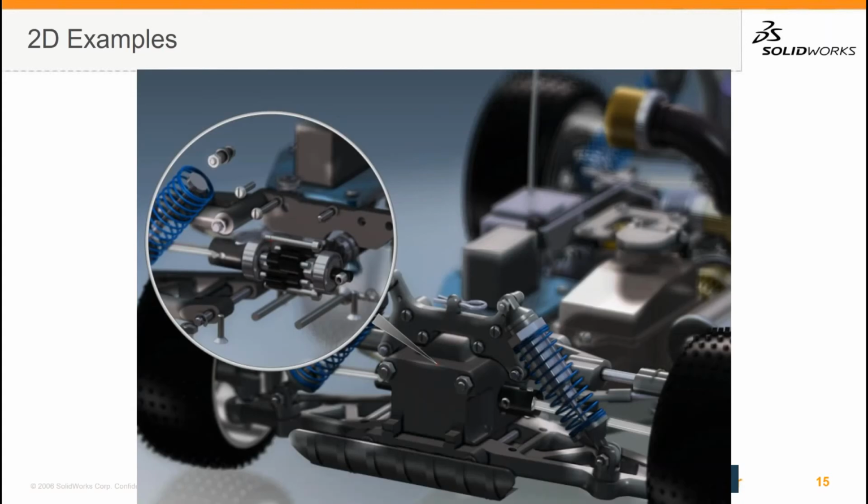And then we do even have rendering tools inside of Composer too, to do images like this. Set a depth of field to blur the background, a nice zoom tool here called the digger tool to show detailed information and dig down into a model, and then the ability, of course, to add materials and lighting and do a rendering.